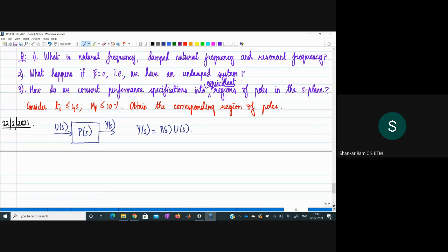So one way to interpret this graphically is that if we have a block diagram representation of this idea, we can immediately observe that if I write the transfer function of a block, the output signal from the block is going to be the transfer function multiplied by the Laplace transform of the input signal.